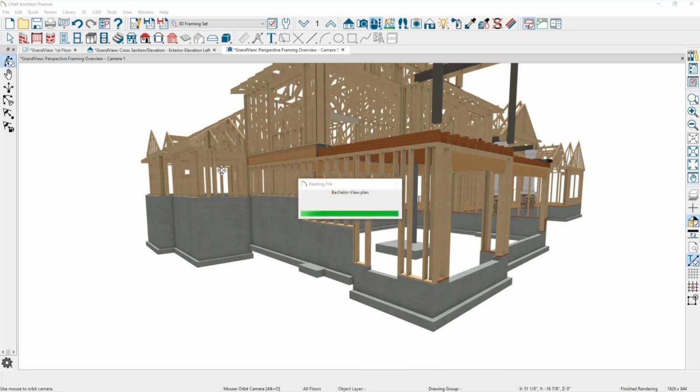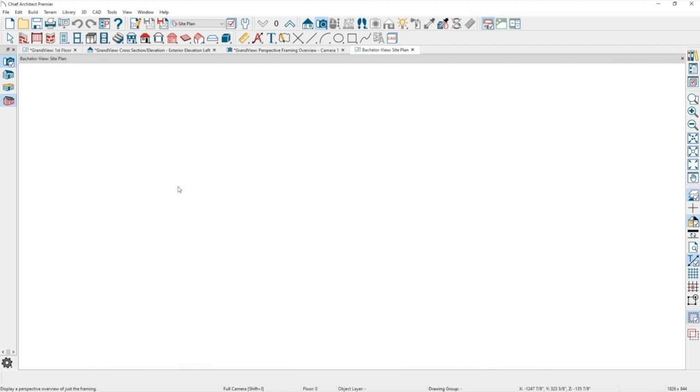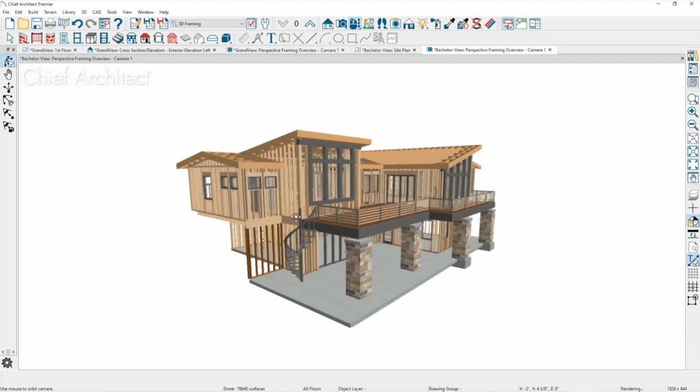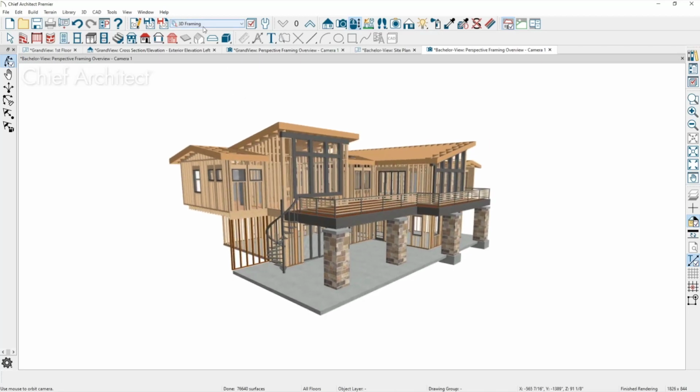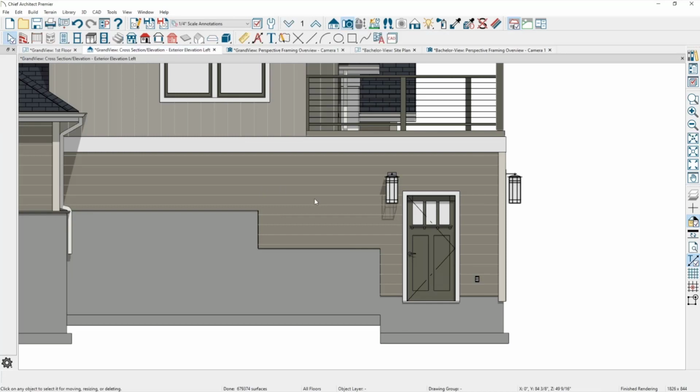Yeah, you definitely don't want to necessarily break your wall type in a plan view, because you're going to separate the wall. And this one, let's see if that has a step down. Yeah, that one doesn't have the same step down that I'm after. But you want to make sure that when you're doing that, you're doing it in the elevation view, because then it's going to be more accurate. That's good to know. Yeah. All right, cool. Thank you very much. You bet. Thank you. Welcome.